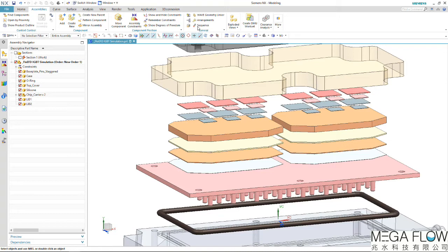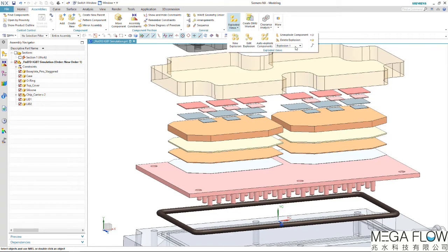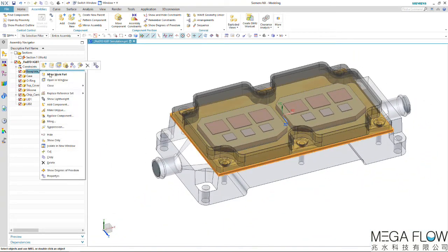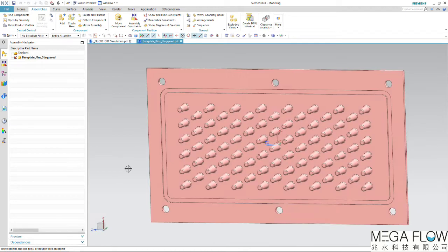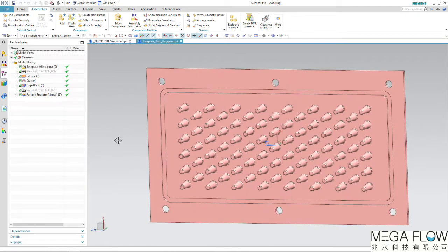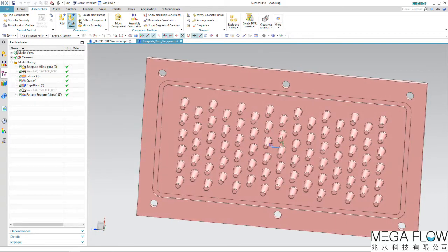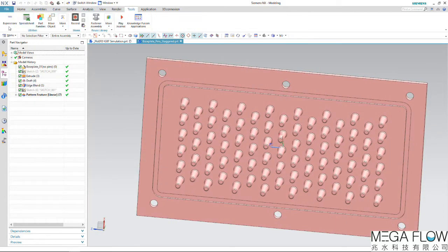the base plate. The casing is made of aluminum, and the whole assembly is designed to operate in vehicle underhood conditions. There is the addition of lids, which serve the purpose of closing the water region and for applying flow boundary conditions. Let's look at the copper baseplate in more detail. If we open the part, we can see it's been designed very simply in NX using an educated guess for its predicted performance.